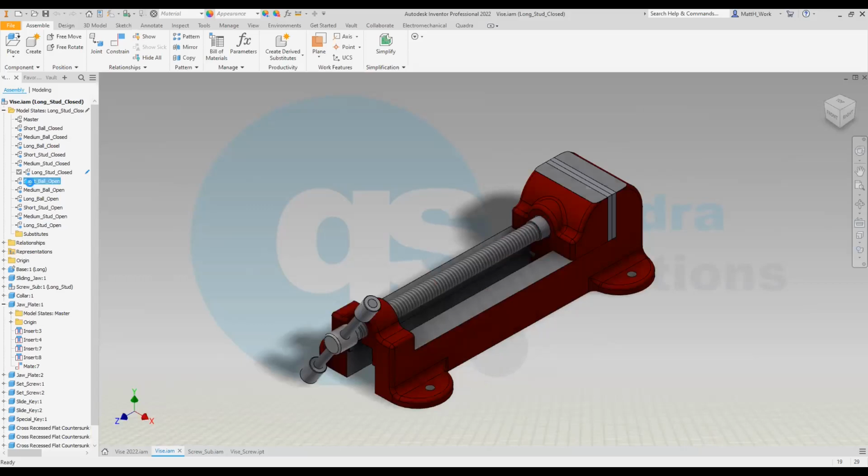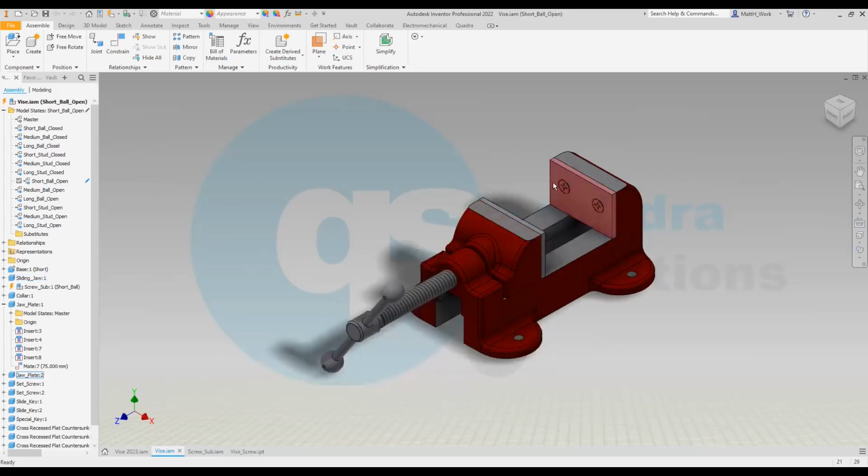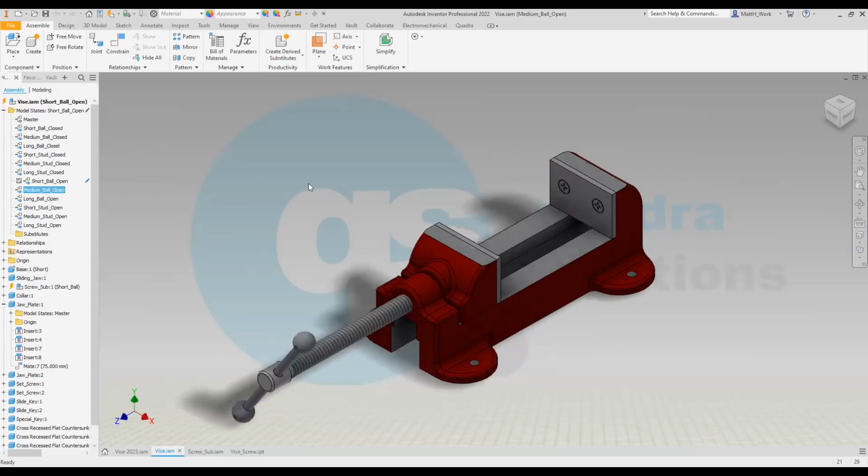I've also included the fact that we can capture the constraint value. It's akin to a positional representation. So I can have the model open or the model closed, but it is not a replacement for positional representation, by virtue of the fact you don't get your overlay views and such like. So use that knowledge as you deem fit.